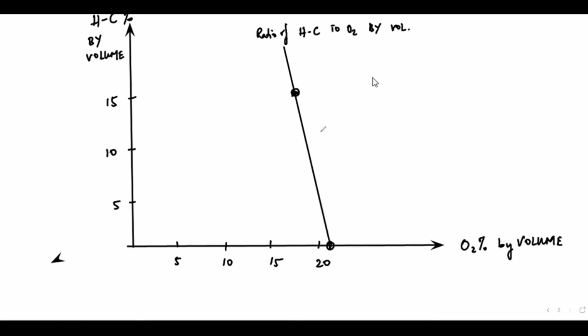So in which condition, if I ignite the gas, is it going to explode or burn? For that, it has been found that roughly around 2% at the bottom, around 10% at the top, and as far as oxygen is concerned, if it reduces to less than 12%, it is not going to happen.